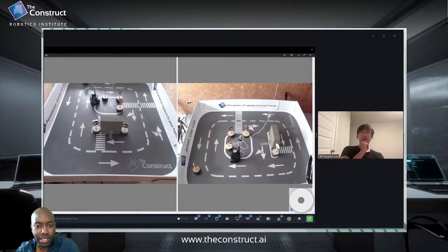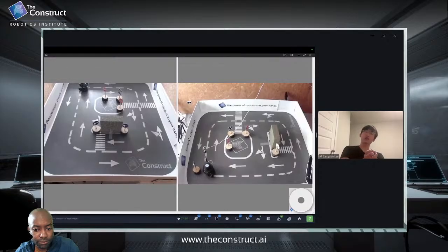And when it reverses, how did you choose the distance that it has to go for? Because I see it almost crashed into the wall, but it stopped, right? Are you also taking into consideration the laser scan data for the back of the robot? Are you considering those for obstacle avoidance as well, to make sure that when it reverses, it doesn't hit an obstacle? True. So I should have thought about that. I should have added the back ranges. When I have that logic, the way you apply the same formula for distance to move, time to move, just make sure it stops when it reaches that point. I should have added that.